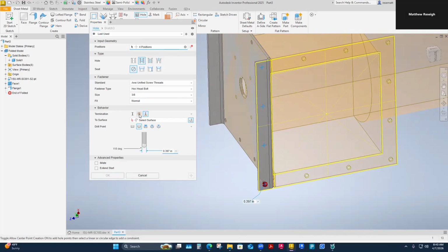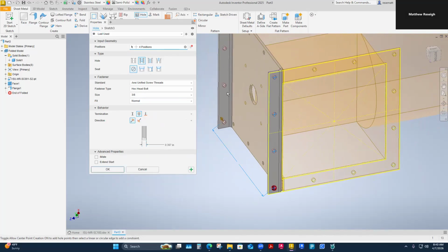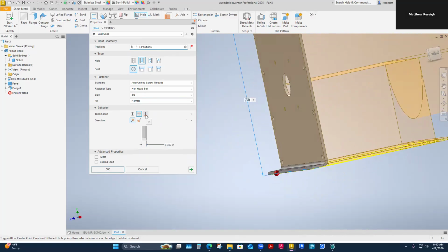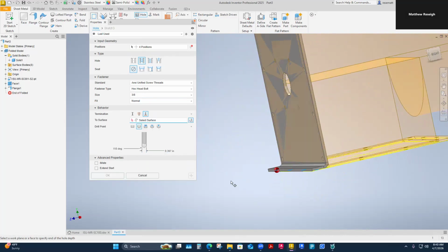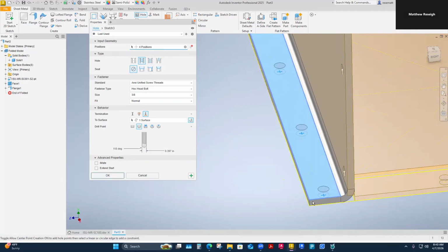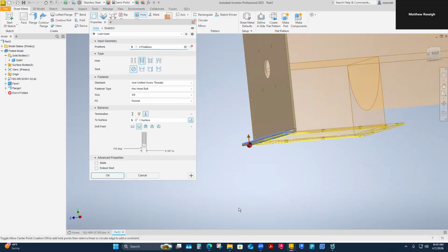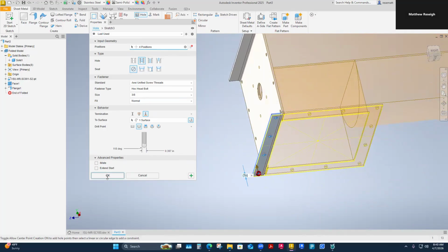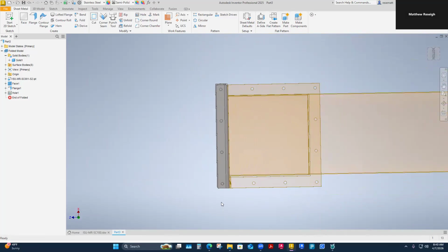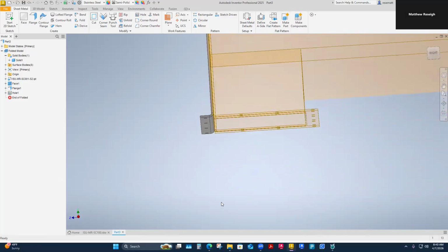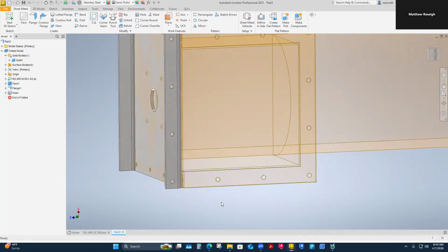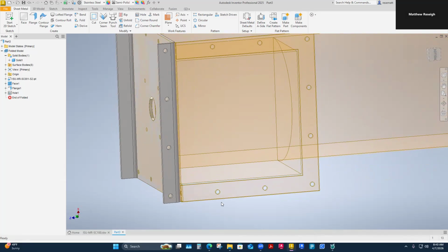And then if I go through all, it'll definitely shoot through my top flange. I don't want that in this case. So I'm going to use my surface feature to next or whatever. And this is the only surface I want to have holes from my sketch up to. So that's a use of that command. And then I'm just going to say okay. And I've got a completed hole pattern flange there now. That's kind of unusual, but not totally unusual, but this is kind of a unique situation where I use two parts to make the flange.